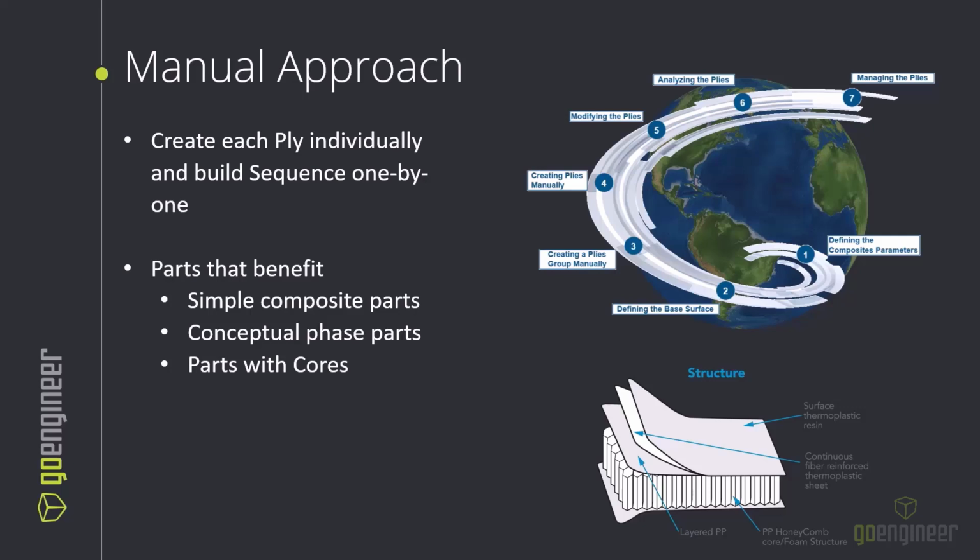So in this method, we take the wireframes that are on our surfaces, typically made of intersections once again. But instead of developing a grid in our cells and so on and so forth, we're using those wireframes to first develop the contour of our plies. Once we've developed the contour, then we assign a material and a fiber direction. And then we repeat that process for the next subsequent plies that we're using on that part.